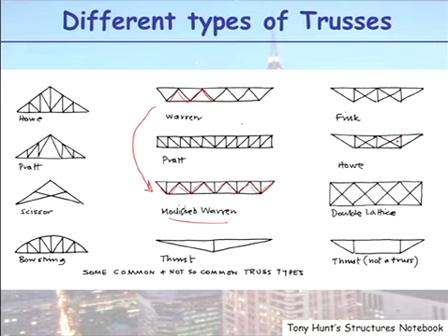passed. Okay, and these spans of rivers were too far for beams. In England, they would build a nice old arch bridge out of stonework. In America, they wanted to move east quickly. So how do you make a quick structure to span a river? Out of timber. So a lot of these truss bridges in America were built out of timber. So it's the railroads in America that actually helped develop the usage and the development of all these different truss designs. So Fink and Howe were 19th century engineers or builders of bridges.